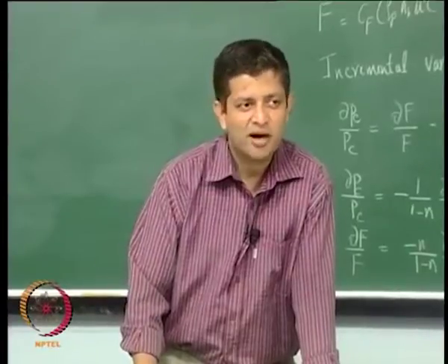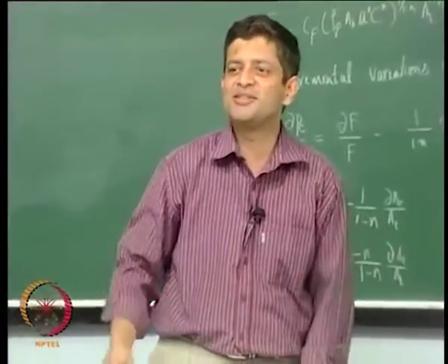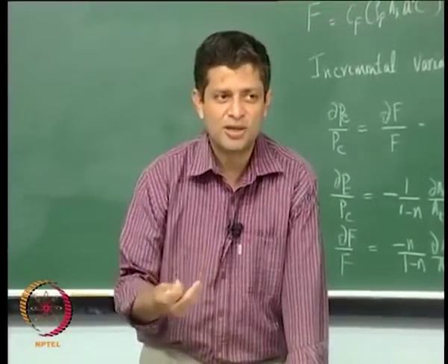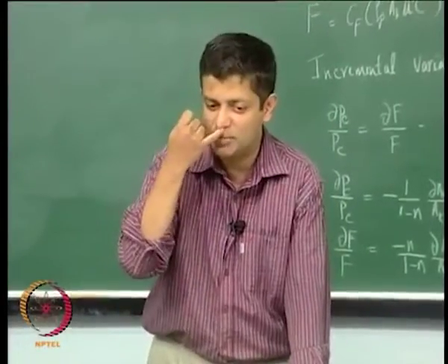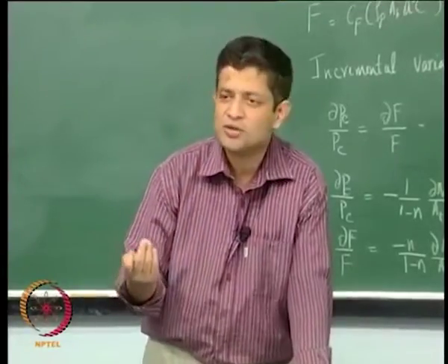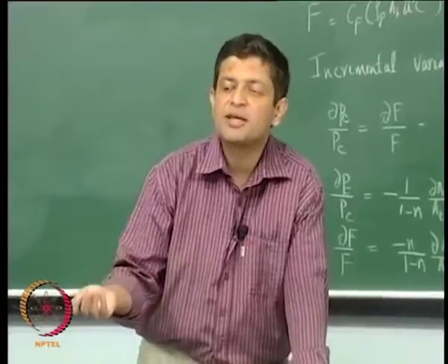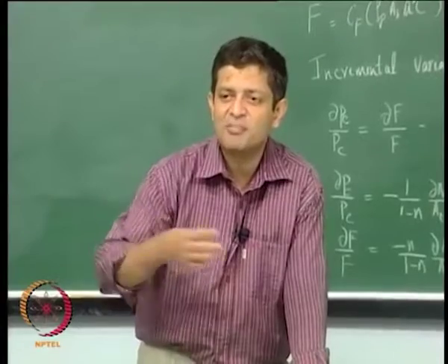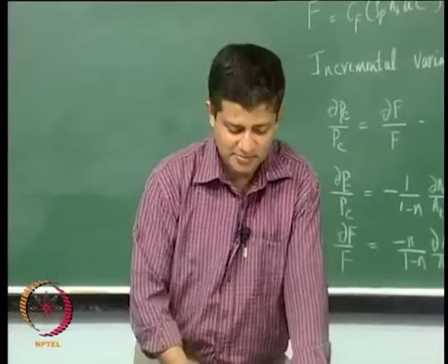But if you have too many segments, then your reliability in some sense goes down, and you are also exposing it to, in some sense, combustion instabilities, because you will have some protrusions coming in because of the liner, and that is something that you would not want. So, it is, in a sense, give and take between these two.